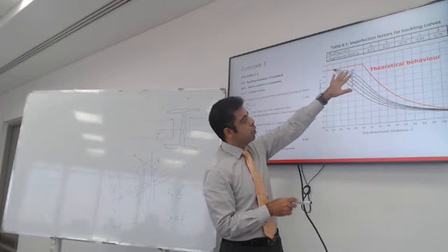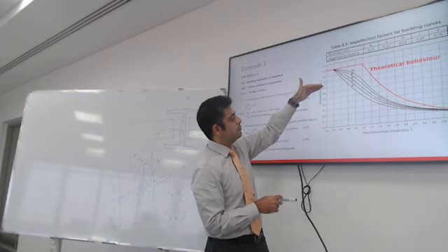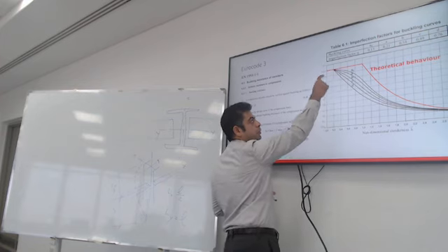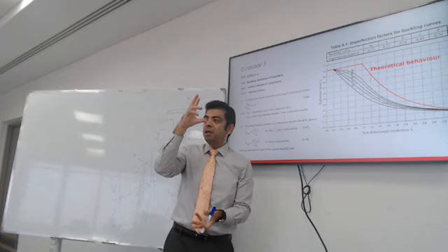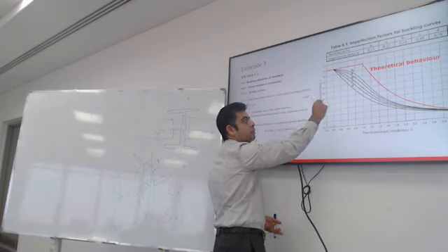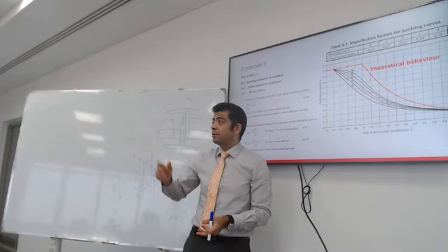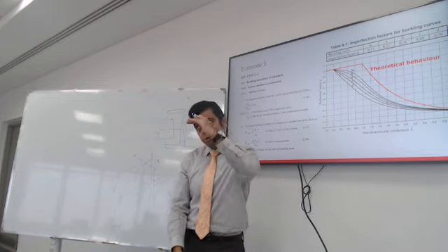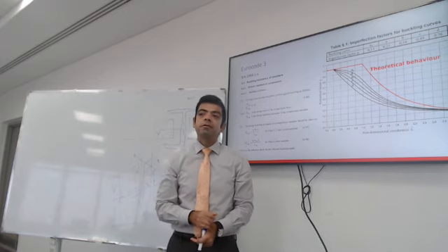As you go deeper, there is a reduction in the capacity. So these factors will reduce the capacity. If the reduction factor is like 0.9, you take 90% of the stress on the column. If the reduction factor is like 0.2, you take only 20% of the capacity. So you slash down the capacity. You could be using a lot of steel, but because your column is so long, you can use just a fraction of the yield stress of the column.